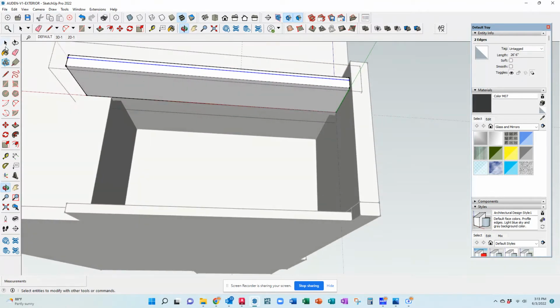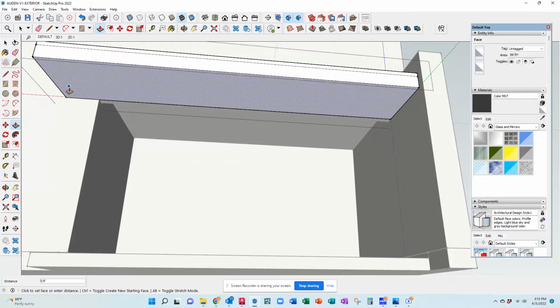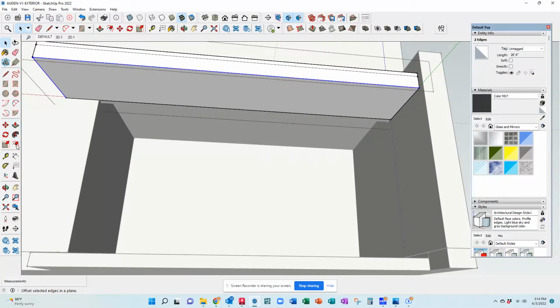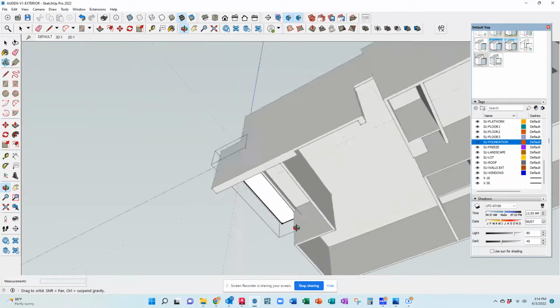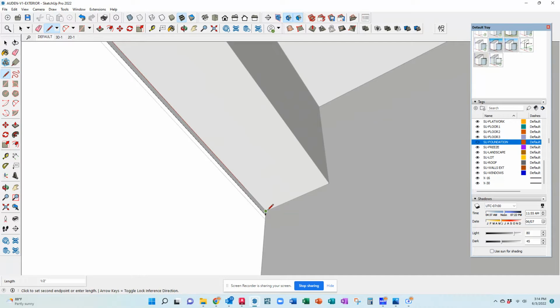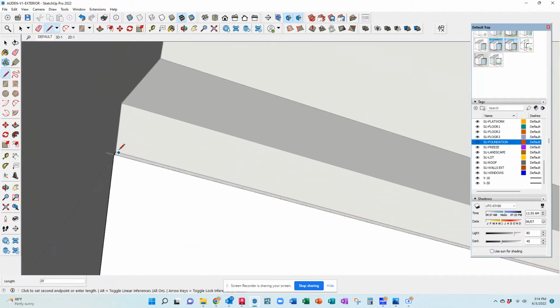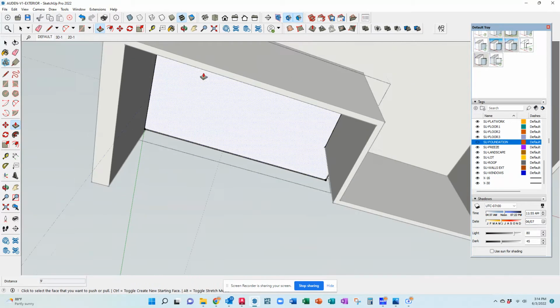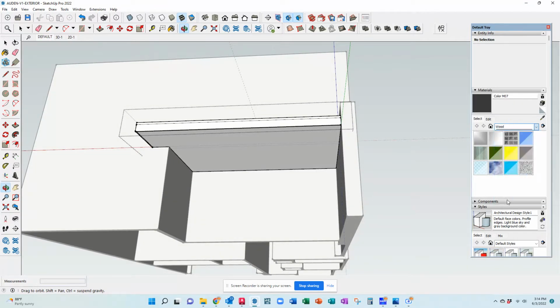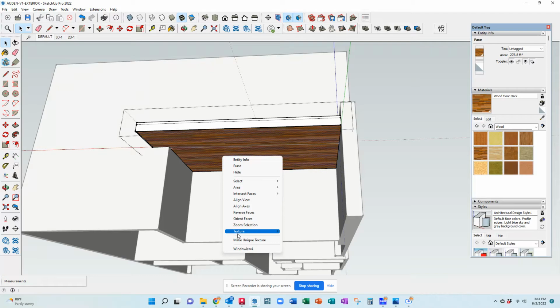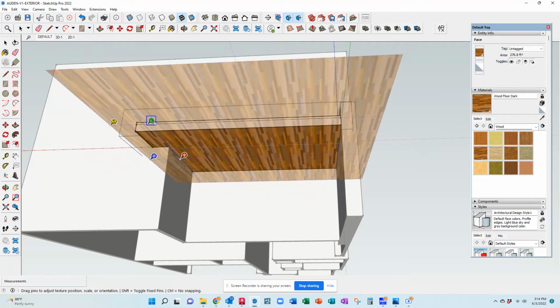Here at this point, I'm doing a roof overhang at a rear covered porch. Again, because of the modern nature of the design, we want that to be kind of flush and seamless, so that'll have an integrated beam once we get to engineering, and the soffit material will continue all the way from the thick overhang all the way back to the wall without a drop beam interrupting that.